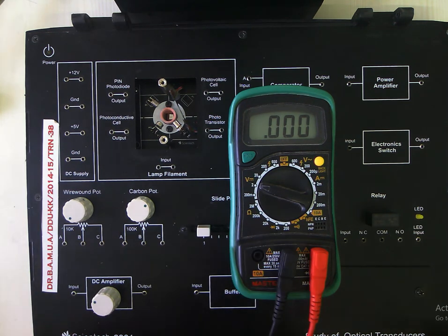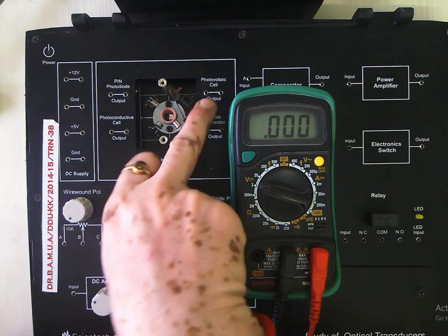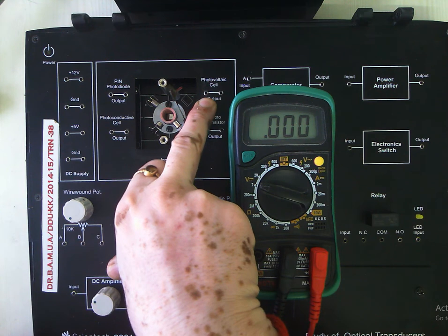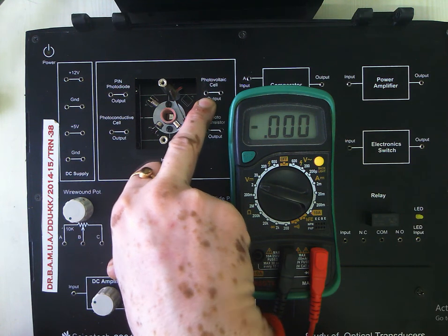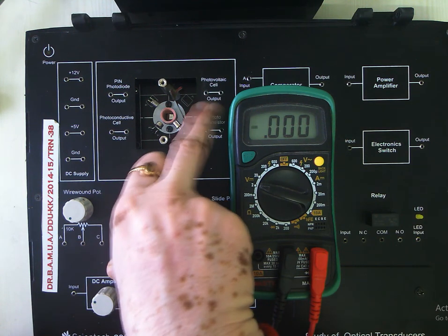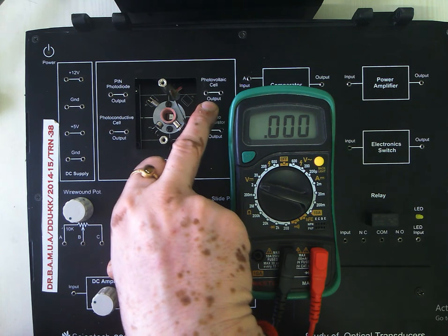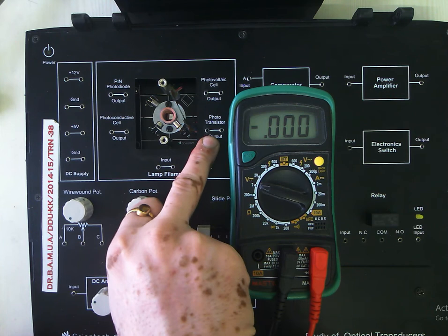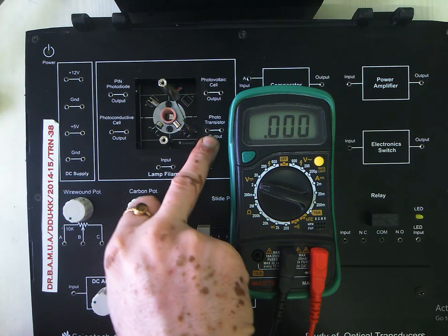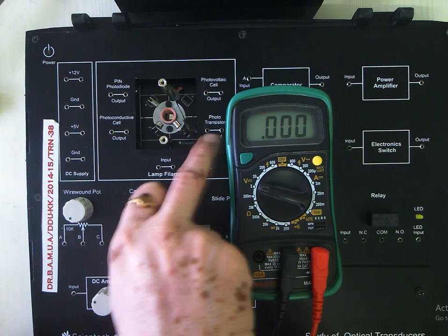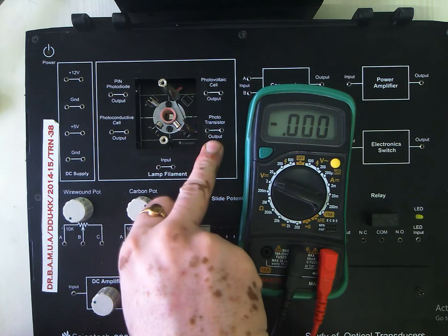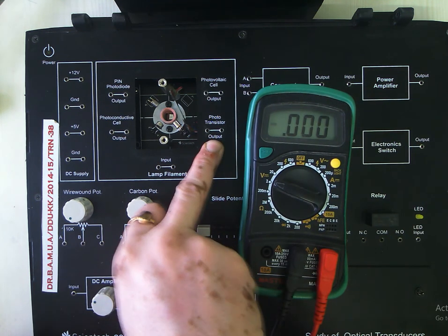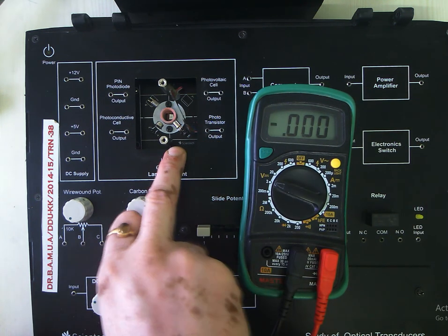All right. Now see how the sensors are connected, because since already they are connected, we might get confused. You see here, one terminal of the photovoltaic cell, it has definitely two terminals. One terminal is available here at these test terminals, and the other terminal is connected to ground. Likewise, if we talk of the phototransistor, these test terminals are connected to the collector, and the emitter is connected to ground again.